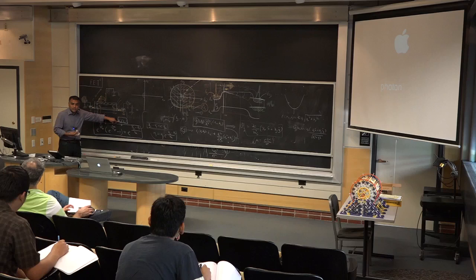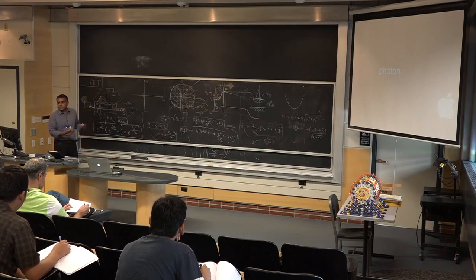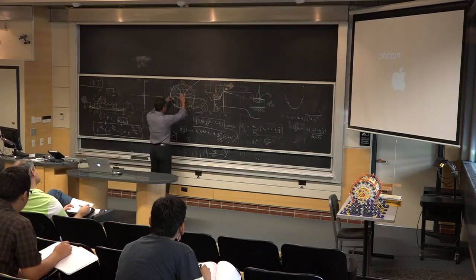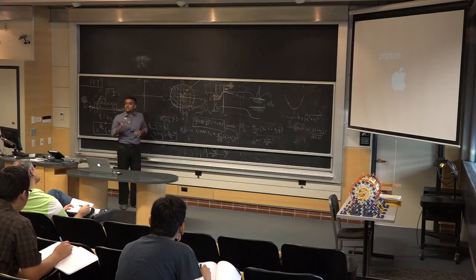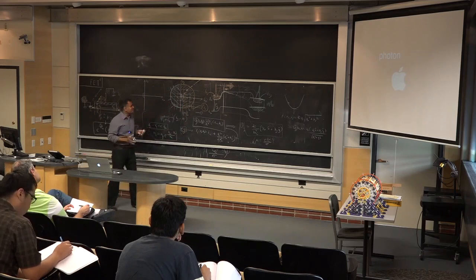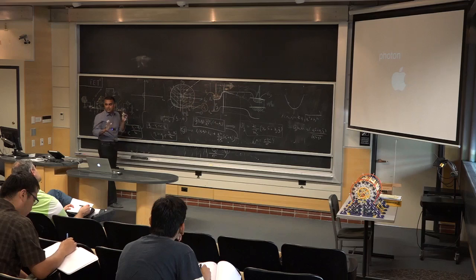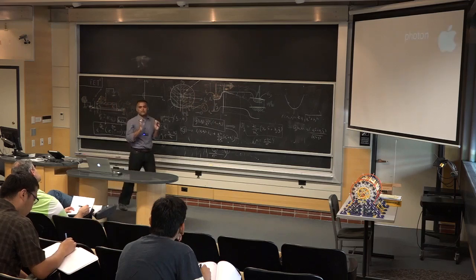If the gate cannot control how much charge is flowing between source and drain, then it's as good as having 3 resistors connected to each other. There is no gain in 3 resistors. This is the heart of the problem. So the gate completely controls. It dictates the total area, because the total area is the carrier density. And source and drain only control how carriers are distributed in K space. That's all the control. Does that make sense? This is actually a very important point.